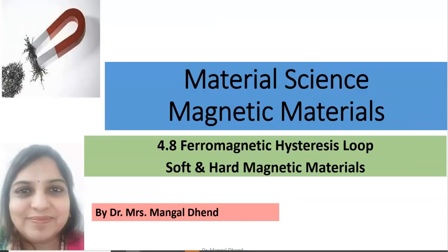Okay, so in the last session we covered a very popular ferromagnetic material. Now I want to discuss the properties of ferromagnetic material in detail, the relationship between B and H, which is very essential for understanding. We have measured flux density with a Gauss meter. Now let us see what hysteresis is. Hysteresis means lagging behind. It is the relationship between flux density and magnetizing force H.